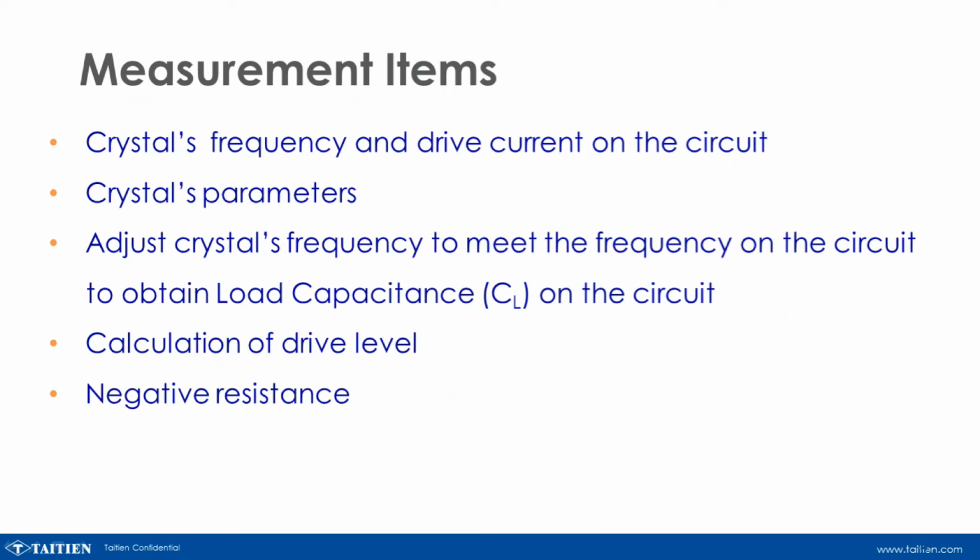And here are the major items need to be measured. First, it is the crystal's frequency and drive current on the circuit. Next, it will be the crystal's parameters. And then we will adjust crystal's frequency to meet the frequency on the circuit to obtain the load capacitance on the circuit. Then we will calculate the drive level and negative resistance.